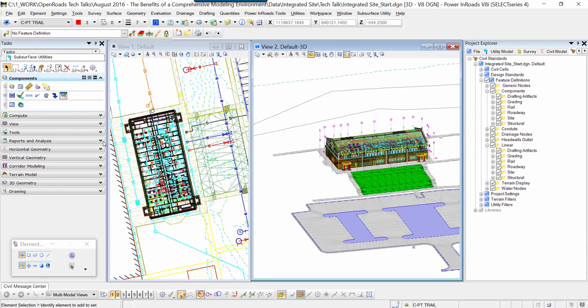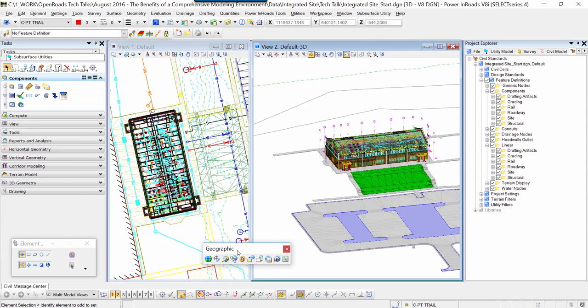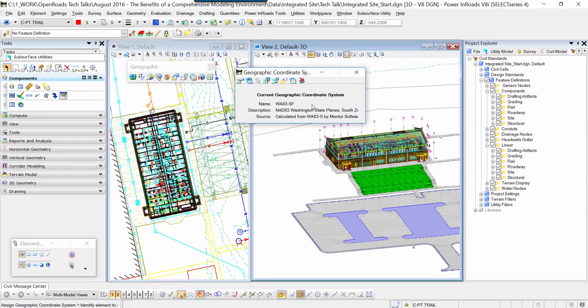Within that building model, there are geographic tools, and I'll give you this tip. Many of you have probably already set a coordinate system inside your DGN. A DGN can literally have a state plane coordinate system, which defines the X and the Y relative to that zone within whatever state.